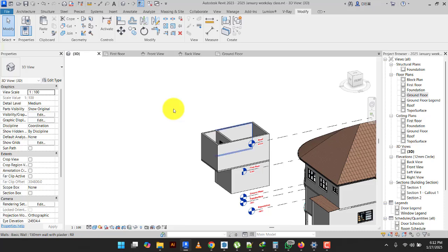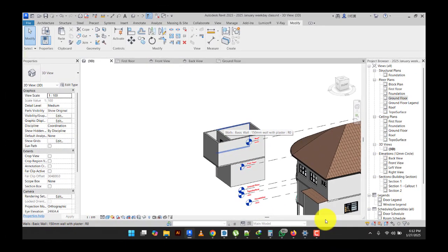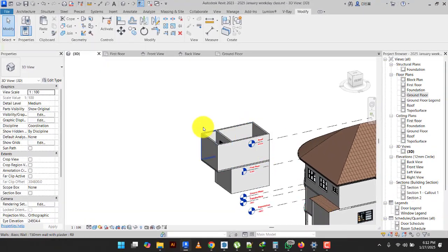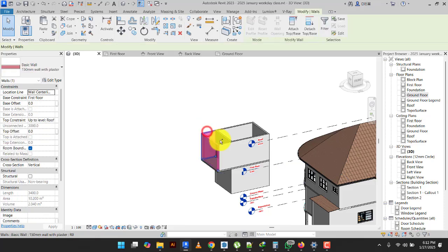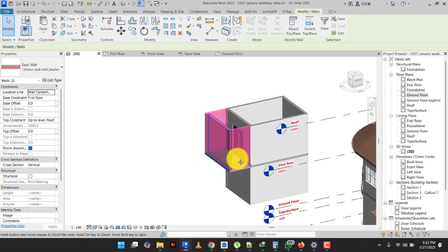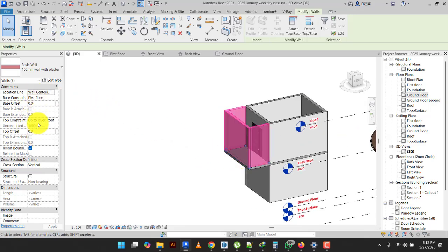Did you see the split? So these three walls. One would control this and that. You can play with the parameters here. You see we have base offset. So just give it a base offset to go up. It's positive. I know the height of the level is 3,000.